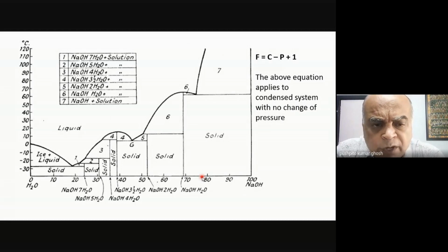It therefore becomes also important for us to understand, because what am I trying to do? I am trying to convert liquid solution of sodium hydroxide. I'm even ignoring the sodium chloride, and let's say I'm trying to make caustic lye. I have to understand, is it a very simple process? If you're ignorant, yes, it will be a very simple process. You will think, hey, let me keep evaporating water. Somebody says, it's an alkaline thing, let us try to do a vacuum distillation and try to remove the water. But the problem is that if you look at the phase diagram of sodium hydroxide with different amounts of water, so what you find is that it is highly complicated.